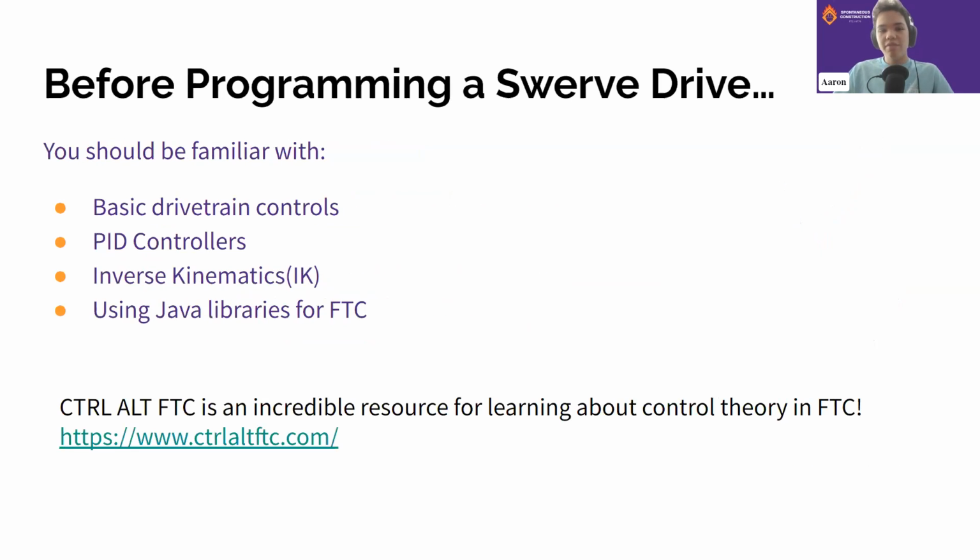Before programming a swerve drive, there are a couple of things you should really be familiar with. First of all, basic drivetrain controls, like how you take an X and Y input from a joystick and convert it into a mechanism input. This is really useful because those drivetrain controls can be reused for basically any sort of drivetrain in FTC, and of course that helps a lot with learning swerve drive controls.